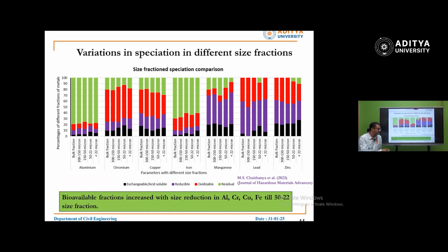So what are those conditions? For example, a change in pH level. Even a small change in pH level, during those conditions it will also come out under reducing conditions. For example, when we discussed the study area, I told you that the study area is receiving domestic discharges from the nearby villages. If the study area is receiving domestic effluents continuously, that means they are highly oxygen demanding waste. So this lake is already under reduced condition. So chances are more for leaching of metal in that particular reducible form.